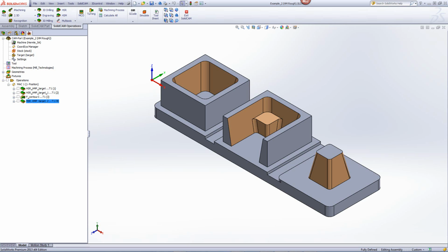HSM, however, is 3 axes, and that does work simultaneous. But what you need, if you want to do a statue which is like a 5 axis, that you need the 5th axis module, which is not HSM, which is actually our simultaneous multi-axis machining, which will have a different webinar on that.